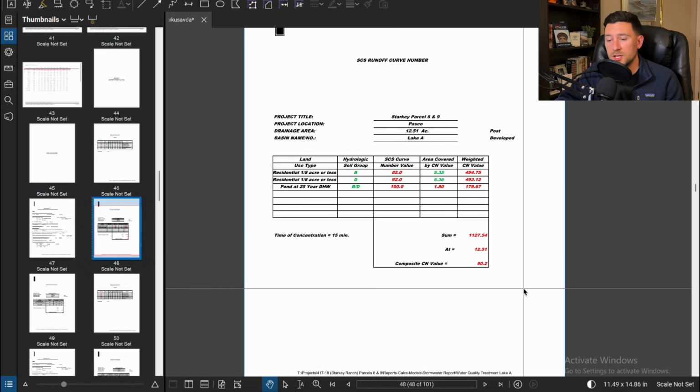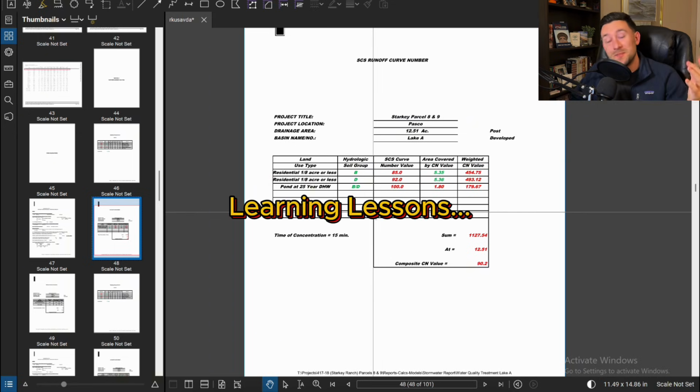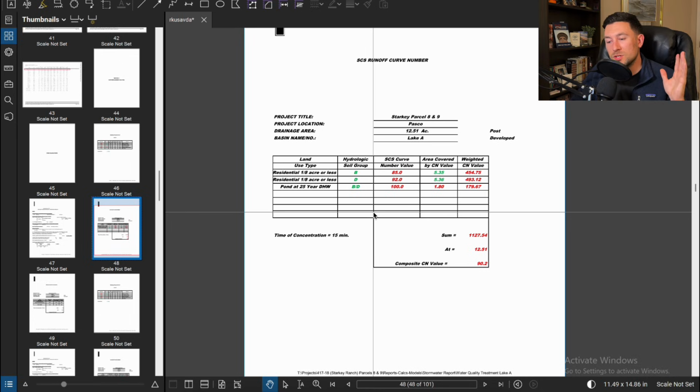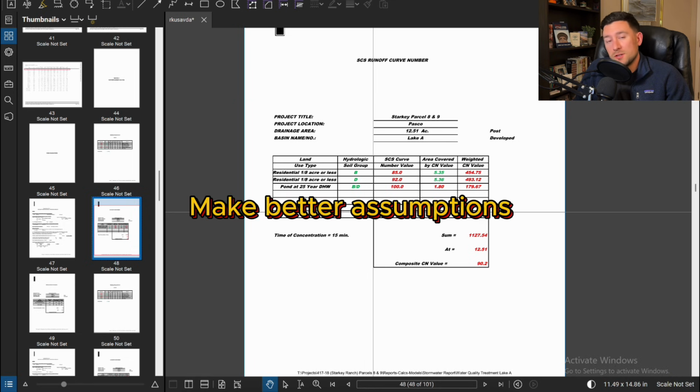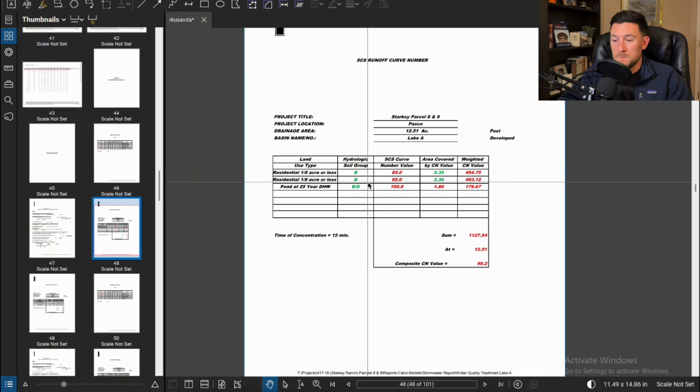Lastly, you have your CN calculations. It's really always important to understand the land use type. One learning experience, okay? Everyone makes mistakes, right? I think one of the biggest mistakes I have ever made is I was doing a master model. I was working on it for like a month, and I was using a very, very low CN value of like 60 for a residential neighborhood, which really, it's up to you, but it doesn't really make sense because residential is going to have a little bit more impervious area. There's buildings, there's roads. So a learning lesson there is do not screw up your curve number calculations or else you're going to have to redo all your work. So always state your assumptions, ask around, ask your PM, talk to other people about it, be 100% on these.